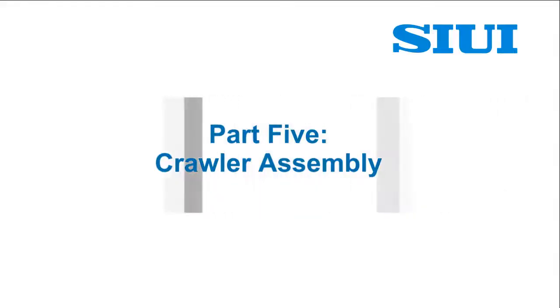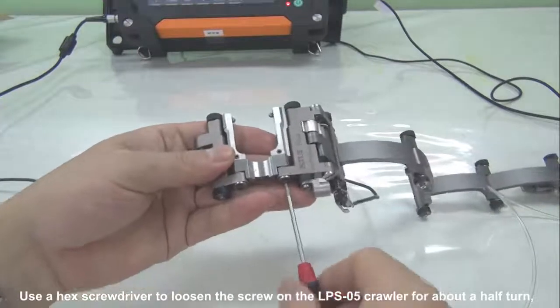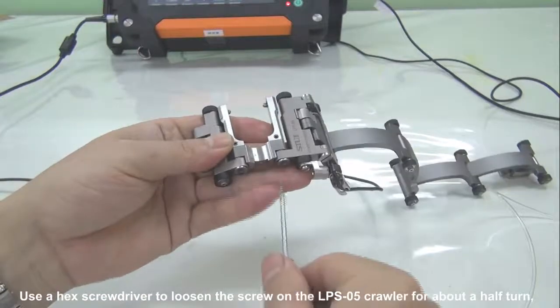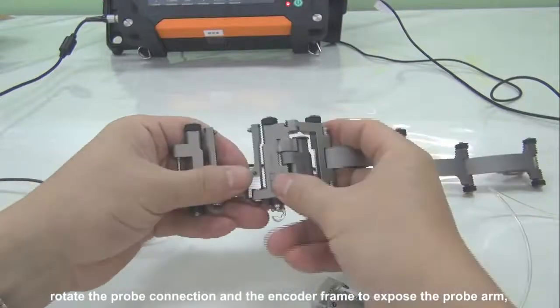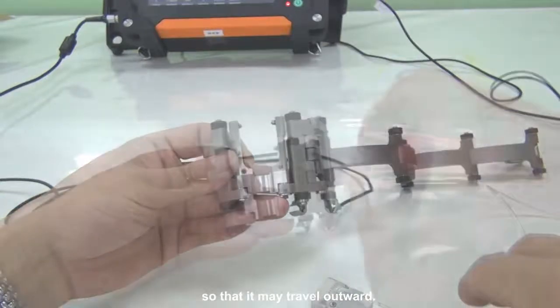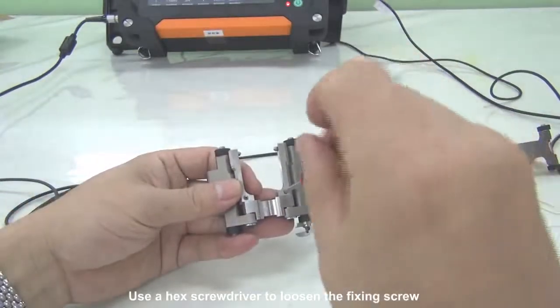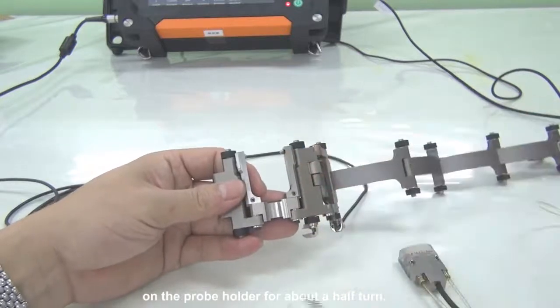Part 5. Crawler Assembly. Use the hex screwdriver to loosen the screw on the LPS 05 crawler for about half a turn. Rotate the probe connection and the encoder frame to expose the probe arm, so that it may travel outward. Use the hex screwdriver to loosen the fixing screw on the probe holder for about half a turn.